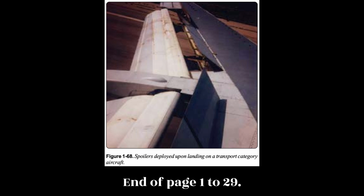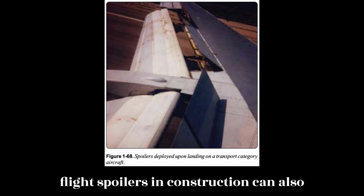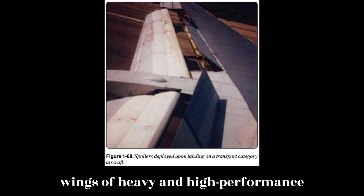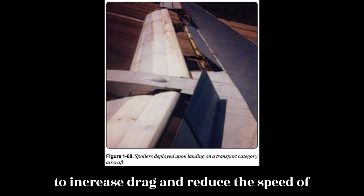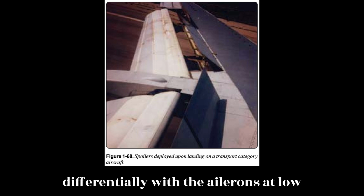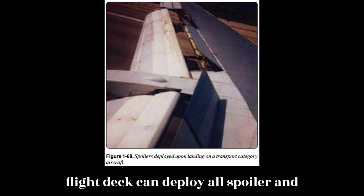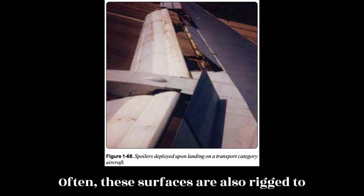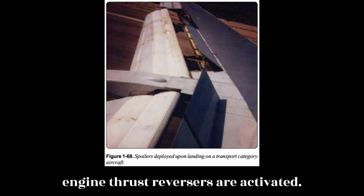End of page 1-29. Dedicated speed brake panels similar to flight spoilers in construction can also be found on the upper surface of the wings of heavy and high-performance aircraft. They are designed specifically to increase drag and reduce the speed of the aircraft when deployed. These speed brake panels do not operate differentially with the ailerons at low speed. The speed brake control in the flight deck can deploy all spoiler and speed brake surfaces fully when operated. Often, these surfaces are also rigged to deploy on the ground automatically when engine thrust reversers are activated.